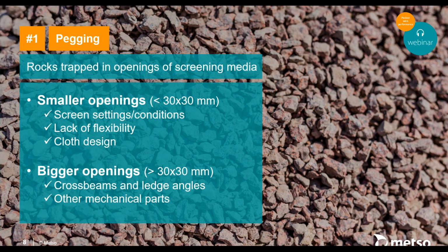When we talk about bigger openings, typically way above that limit, it's often the case that the rocks cannot pass through the screen media because there are mechanical parts in the way, let's say ledge angles, cross bracing, cross beams, and other parts limiting the ability for the rocks to pass through the deck. And that's actually very common. So we will look at a few examples in that area as well.